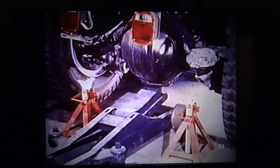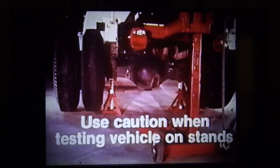If the disturbance continues, raise the chassis and support the front and rear axles on safety stands. In some cases, the safety stands will dampen the vibration from the rear axle. It is often necessary to raise the vehicle off the rear axle stands a slight distance and support the rear of the vehicle with safety stands positioned under the rear of the frame. Extreme caution must be exercised when the vehicle is operated in this situation.